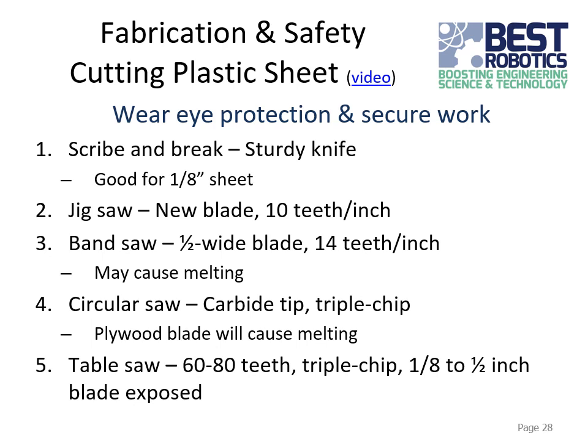So there are a couple different options for cutting plastic. One option that is pretty basic but can work well is just cutting it with a knife and then breaking it. This is good for really thin sheets. You can just use a straight edge and cut it with a utility knife or something sturdy, and usually you'll make a score along it the first time. If you have a nice deep score, you can put a solid edge along that score line and break it off all at once. So that can work well.